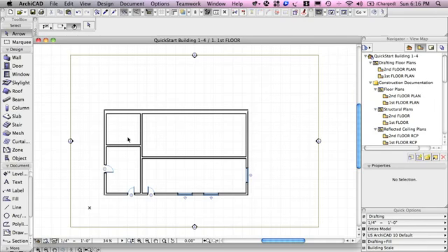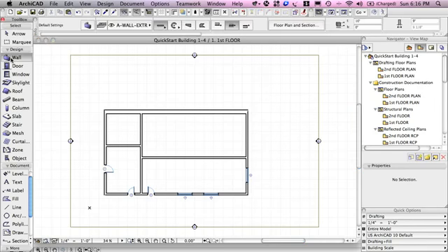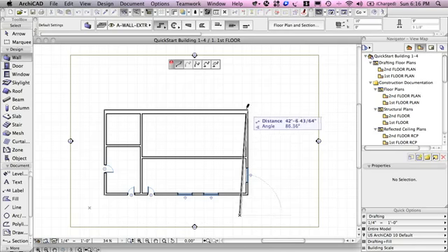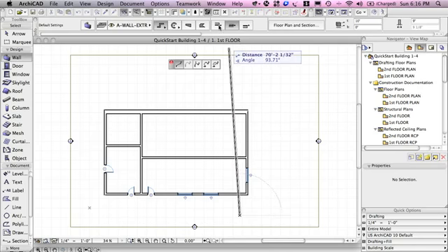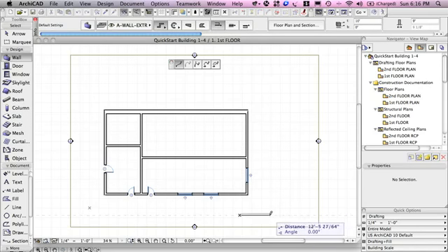Now let's take a look at drawing some walls separate from the current building shape. And I'll draw, let's say, a series of walls using the poly wall option. So let me just do this off to the side. I'll just draw a wall. Let me change this right on the fly. I'll say that I'd like to have the construction method be left so that the line I'm drawing will be the outside of the shape. You can see how that changed now.